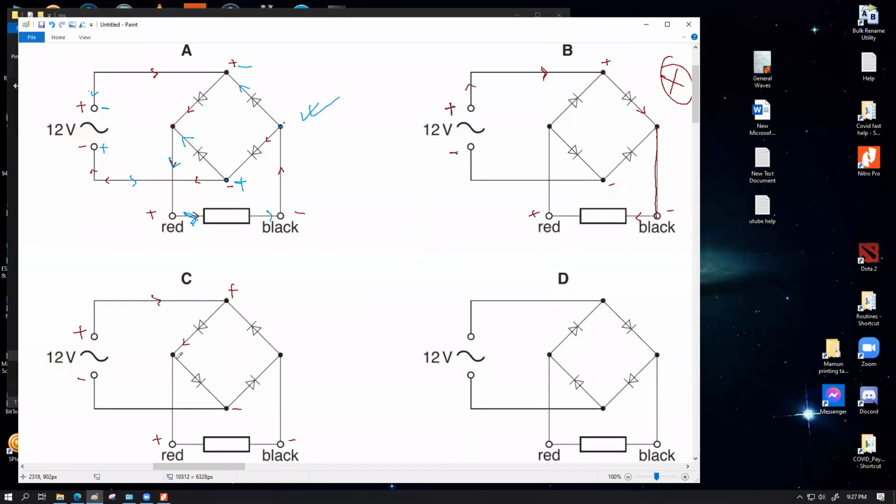And you have to understand one thing. If the current has to flow through the resistor, this is not the shortest resistance path because the current can very easily flow through this path and get back to the negative end of the battery. So there is a zero resistance path that is provided in the circuit, which is not supposed to be available in any circuit, but it just so happens within this circuit you have a zero resistance path, which means at least for this half cycle, current will not at all flow from red to black.